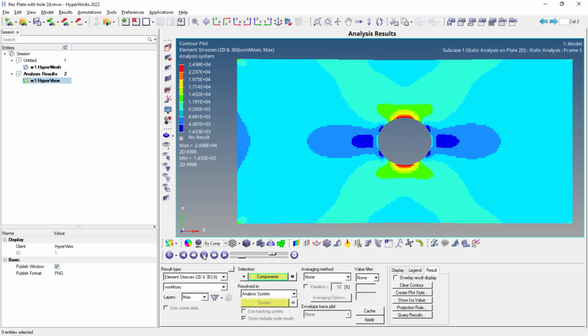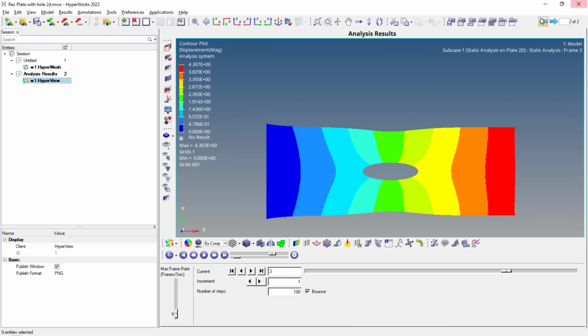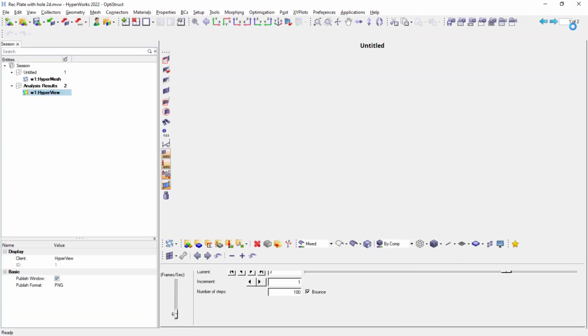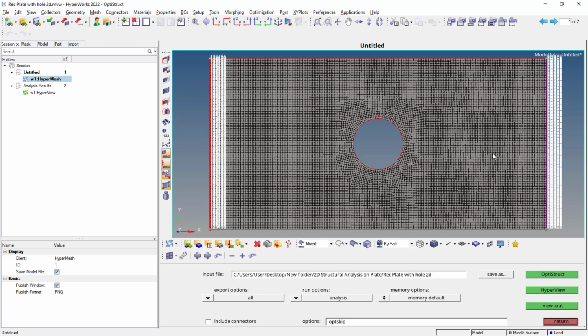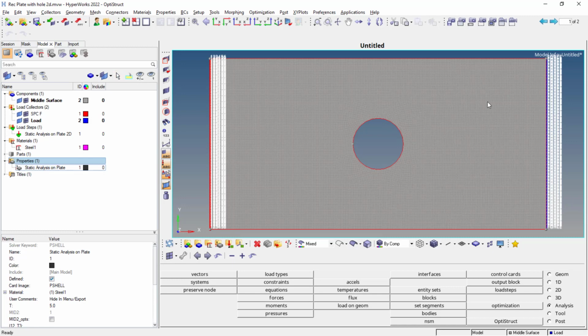While doing the simple basic analysis, some tutorials or some people have showcased the same thing: just select the nodes and distribute the loads equally. Instead of doing this, you can switch to the workbench one by just using the arrow mark at the right corner. Now here, instead of these distributed loads, I'll switch to the model. I'll create the rigid body contact.